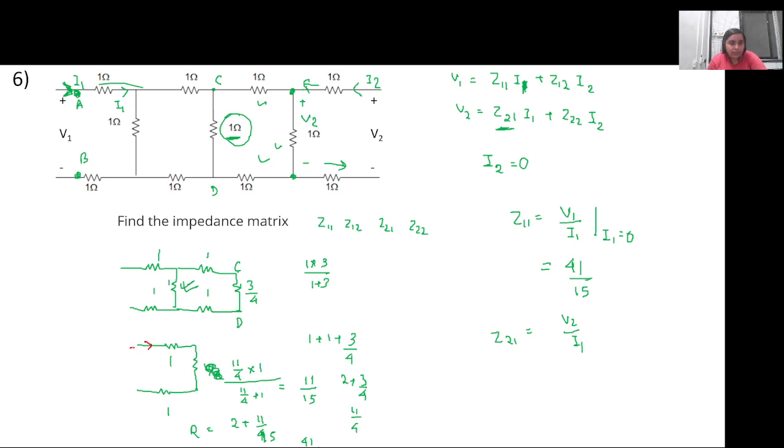In this terminal I1 current was flowing. If we go back to this particular circuit, in which this is the source current I1, whatever the current will get divided among these two branches will be in the reverse ratio of their resistances, right? So what amount of current will be flowing here? If this is I0, what will be the value of I0? I0 will be in reverse ratio, so this 1 ohm resistance by 1 plus the total resistance that is there, so 1 plus 3 by 4, times I1. This is using the current divider rule, right?